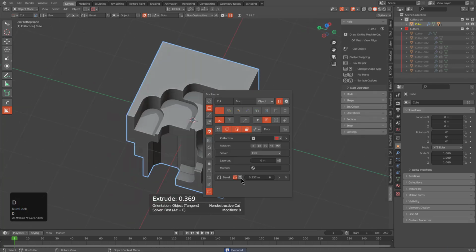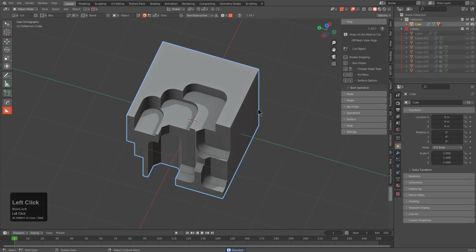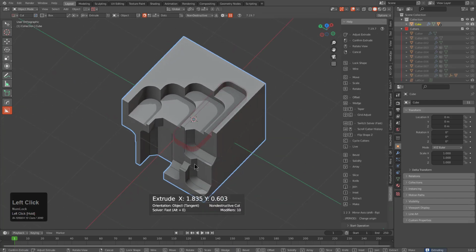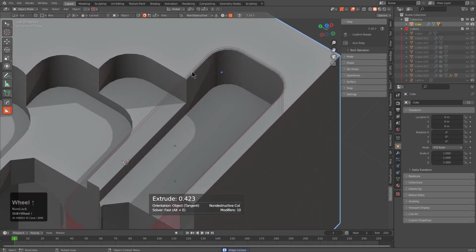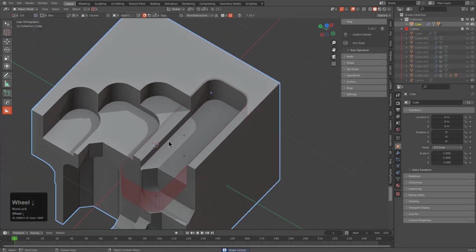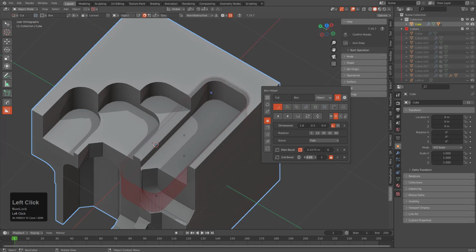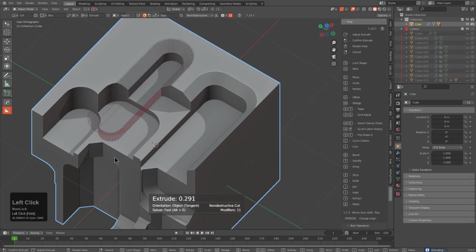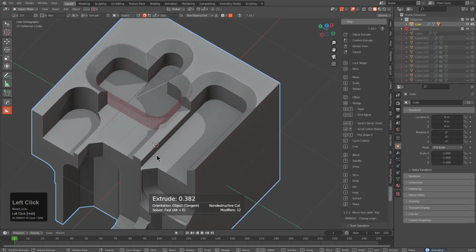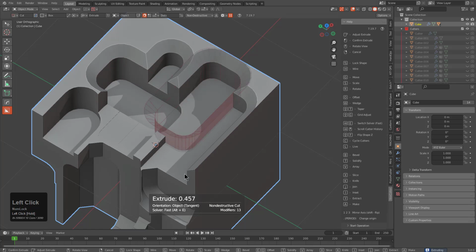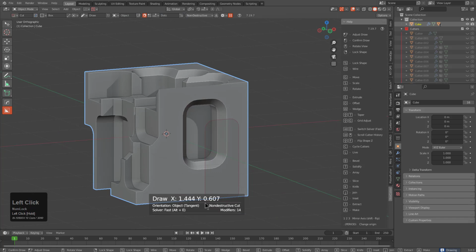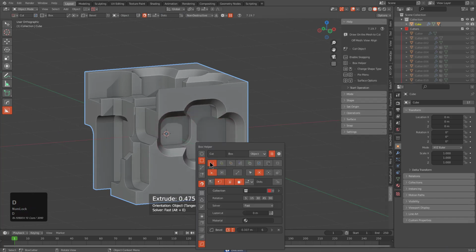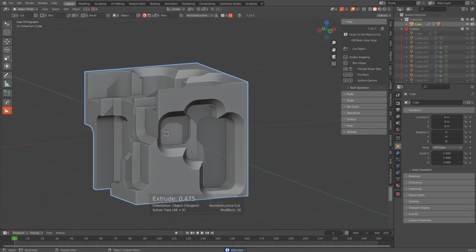The next icon is for the front face or the reverse bevel. So by clicking on that, it means that every shape we draw will have a reverse bevel. However, at this point, you do want to pause it, press D, and go inside the helper and adjust the amount of width, meaning that on your subsequent drawings, you will now have that width take place on your object. So just like that, you're able to jump in and quickly reverse bevel and Q bevel and just standard bevel without having to even press any hotkeys during drawing, just by going into the helper and activating them as start states.